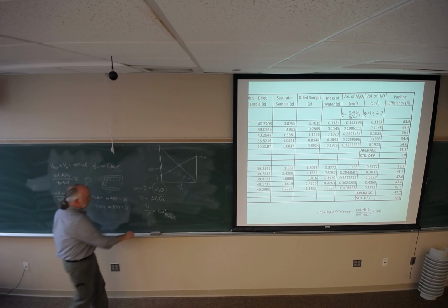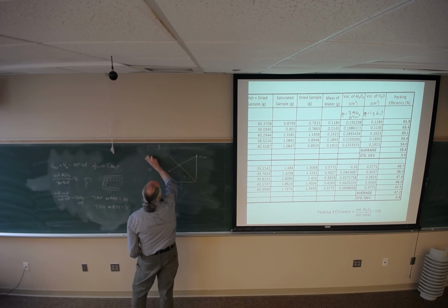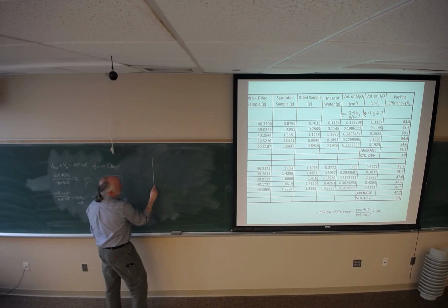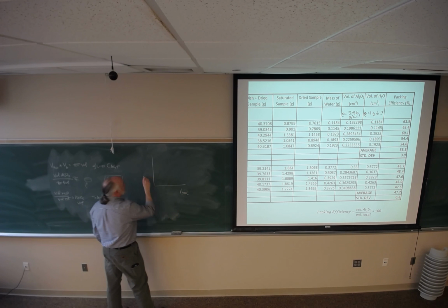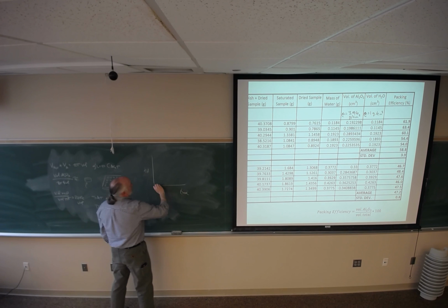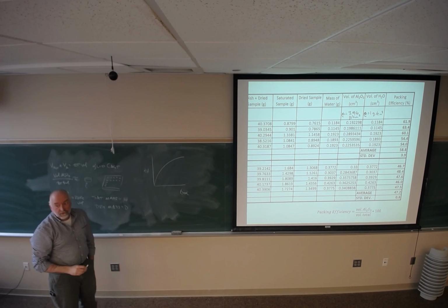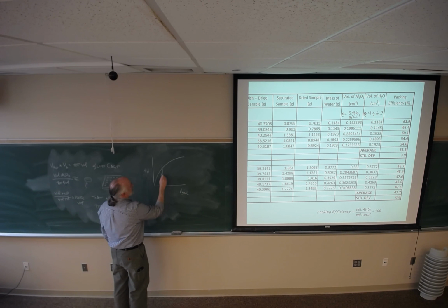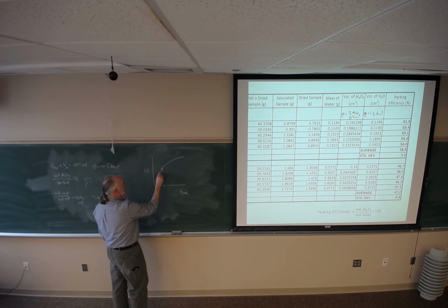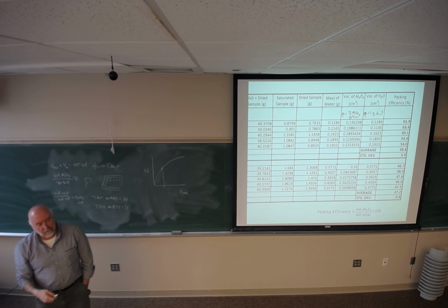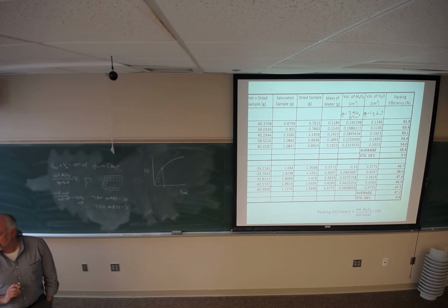Let's talk about casting just for a second. There is a lot of bad casting data out there. If you look at time versus thickness of your cast, the curve looks like that. What people have done, and this is not correct, is fix their time, look at this value, and then go back to 0 and say, that's my casting rate, thickness divided by time. What's wrong with this picture? It's changing. It's not linear, and we were approximating it as linear.